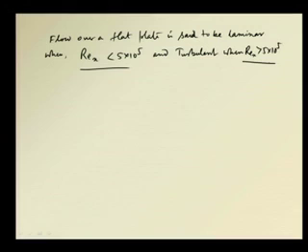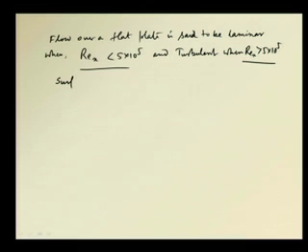Okay. Now, it has been found that these values, this 5 into 10 to the power 5, or these critical values of the Reynolds number where the turbulence takes place, many a time depend upon the surface roughness and various flow disturbances due to various other reasons.